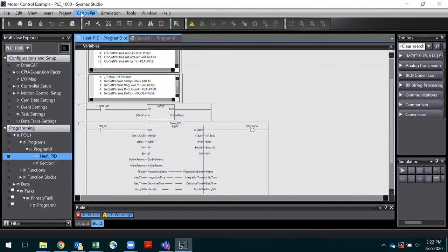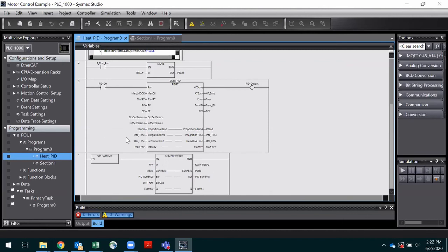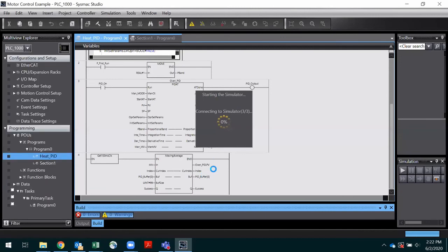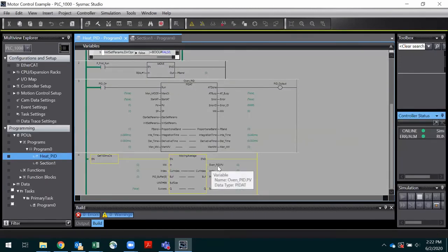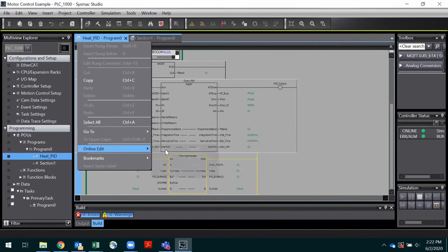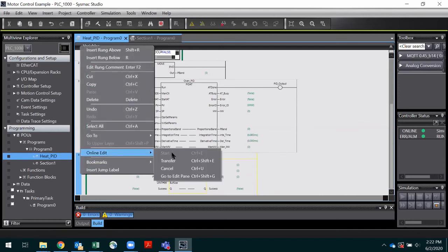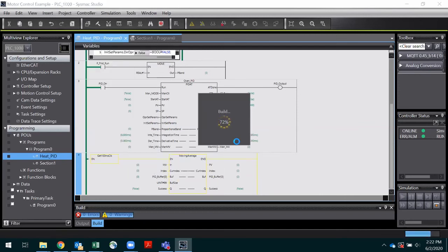I don't know how relevant this is, but I noticed that his moving average is writing directly to the input parameter of the PID rather than the variable we assign to it. Oh, this one here? Yeah, that does need to be changed. The thing that's throwing me off is that that move instruction isn't moving anything into his P band variable.